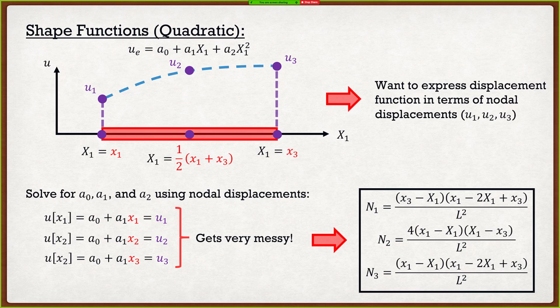So this is why when you guys actually go into your finite element programs, ABAQUS for example, you guys are typically given 2 options: linear elements or quadratic elements. Now, you guys are equipped to figure out what the difference is between them, but you guys will never see cubic elements. The reason why? It just gets too messy. Everything that you guys need can be done with a linear or a quadratic element.